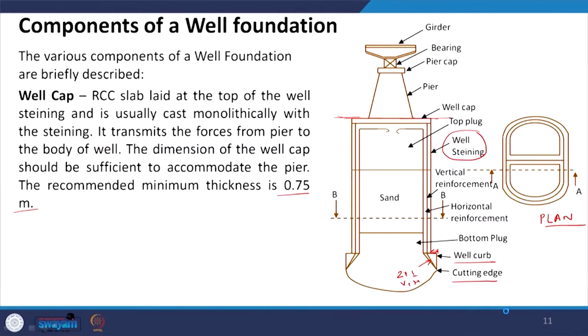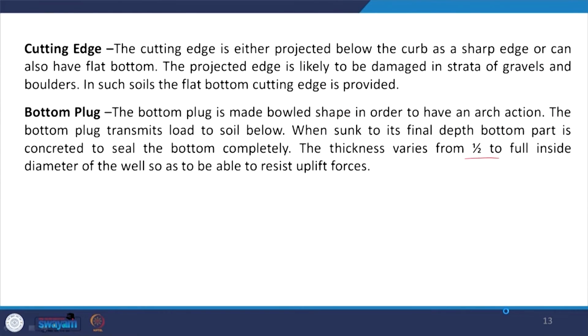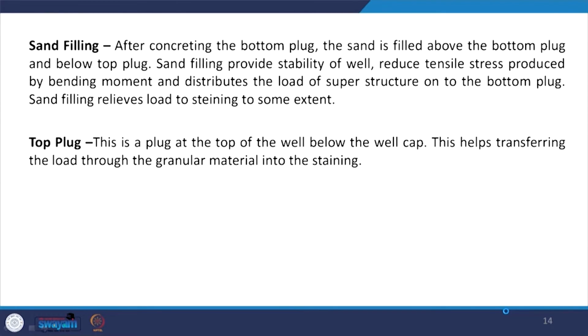So, the well cap also transfers some load directly to the soil, and it will reduce or relieve the load coming on the steining. But still, in case of a well foundation, the major load will be carried by the well steining, not directly by the sand or soil filled inside this well. Okay. So, this is the case there.